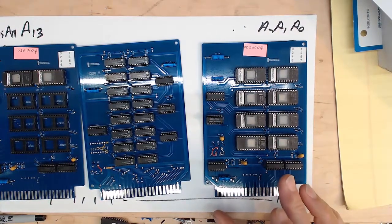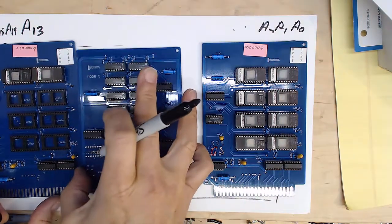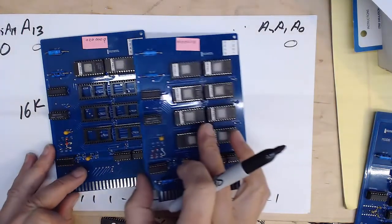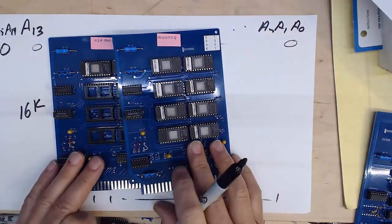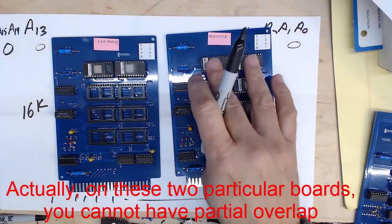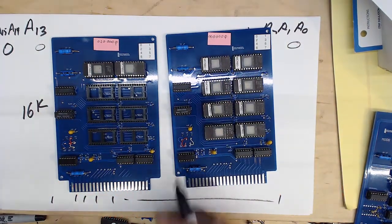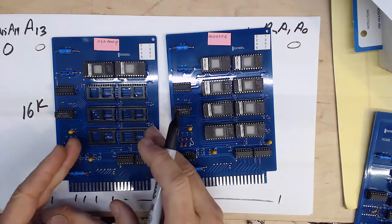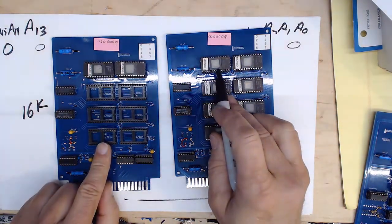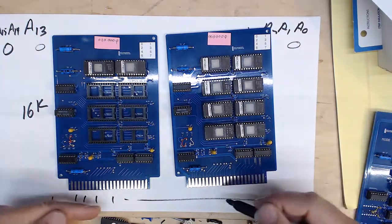Now it's important that only one board is addressed at a time, because let's say that we accidentally picked our jumpers here so that these 2 boards had a little bit of overlap in memory. And so maybe a couple of these chips were overlapped to a couple of these chips. What would happen is the processor would request information from the memory, and that memory happens to be mapped to this chip at the same time it's mapped to that chip. Then both these chips would turn on at the same time, and their bus drivers would turn on at the same time, and they would both be putting information onto the bus.